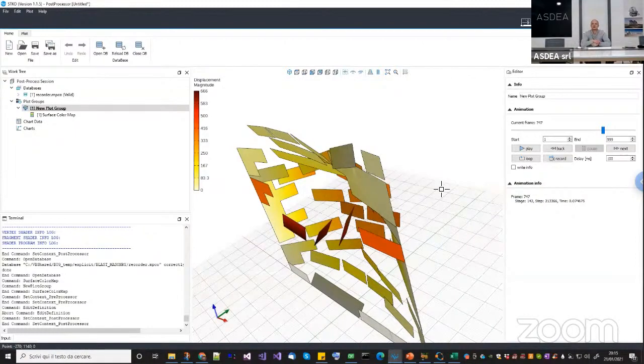In Tcl script, we need to ensure mass matrix inversion is not a trouble, right? Mass matrix inversion is guaranteed if you apply a mass to every free degree of freedom. In that case, the mass will be diagonal, because every element in OpenSees, not only the solid elements, applies a lumped mass approach. If you apply masses at the nodes, it will be diagonal. The only problem is that you have to make sure that every degree of freedom has a mass.